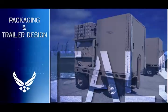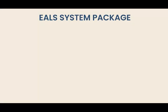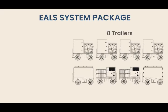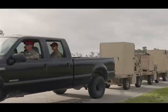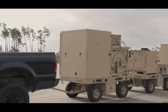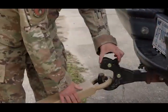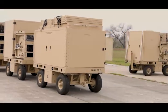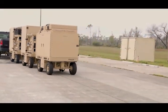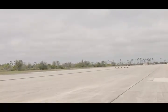Packaging and trailer design. The EALS system is packaged in up to 8 air transportable trailers, which fit within the space of 4 463L pallet positions. The trailers are designed for tandem towing with a minimum 1.5-ton truck, equipped with a pintle hook. Trailers can be towed in a train of up to 3 at a time, supporting efficient installation of lighting equipment and cabling. When towing, do not exceed 25 miles per hour,